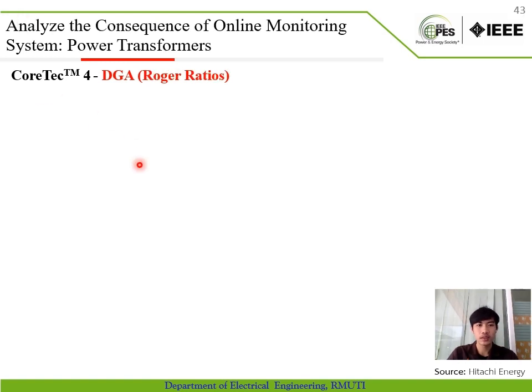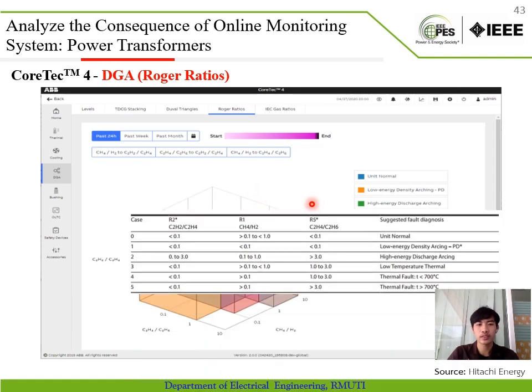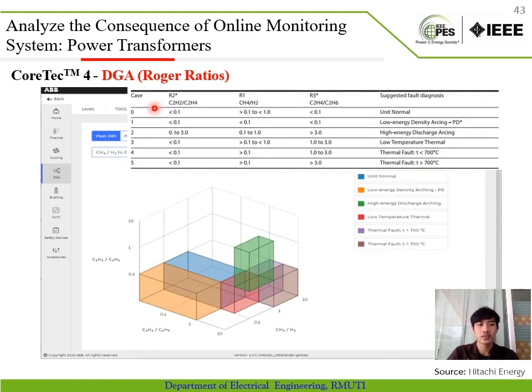And this is the dissolved gas analysis by the Rogers method. And we can analyze this by this graph. On this interface, we can see that it is represented by high energy discharge. And we can analyze this uniformly by the representation of a cube block on this curve. But if we want to make sure, we can compare with the theory ratio standard of Rogers by this